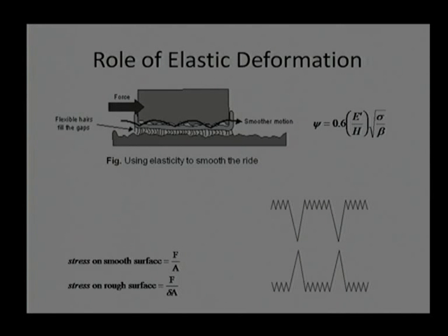There is a possibility of 6 times stress, or another possibility is that if the high stress is equivalent to the elastic limit, naturally the asperities will bend and will allow other asperities to come into the picture. In other words, if the load is more, more asperities will come into contact and reduce the stress back to the elastic limit stress. That is preferable, and maximum in that case, if the whole real area is equivalent to the apparent area, then we can say the component can tolerate that much maximum force.